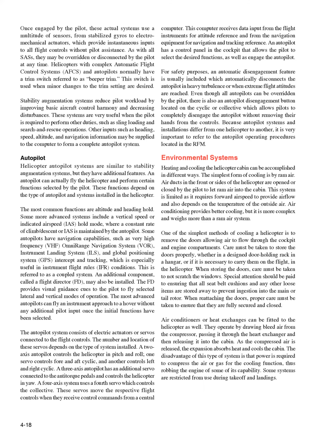When storing the doors, care must be taken to not scratch the windows. Special attention should be paid to ensuring that all seat belt cushions and any other loose items are stored away to prevent ingestion into the main or tail rotor. When reattaching the doors, proper care must be taken to ensure that they are fully secured and closed.